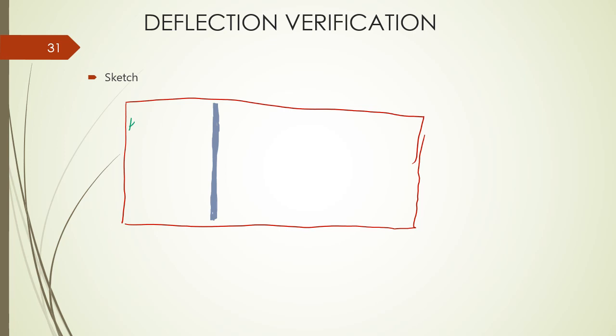And we'll see that this bar over here runs from that edge all the way to the edge of this slab, and that gives us T8 at 250 bottom 1, which gives us 201 millimeter squared per meter.